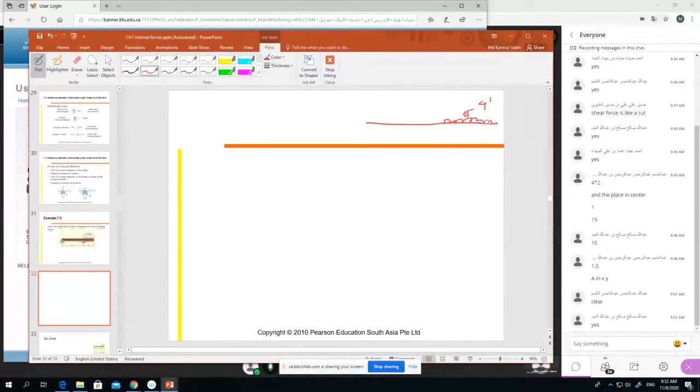So there is 4 kilonewton per meter, and here our forces are PV equal to 10 kilonewton as a downward force. Here was the hinge and here was the roller. Here was RAV equal to minus 2 kilonewton, right? This was 4 meter and this was 2 meter. Now our first job is to draw the shear force diagram.